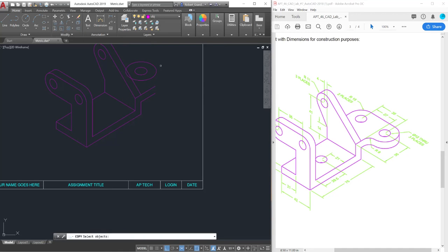So now I'm going to say copy these two this way, a distance of 35, according to the drawing right here. So we can see that's 35. And now, using the same technique I did to create these lines here, I'm going to go ahead and draw a line that goes from the center here to here and move that the correct radial distance of 15 that way. I know it's in the correct location.